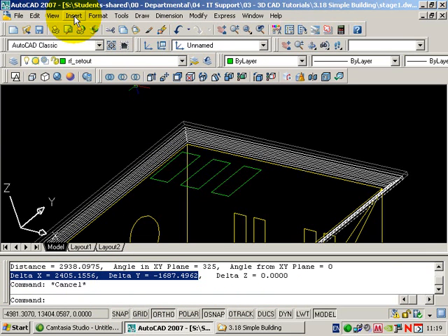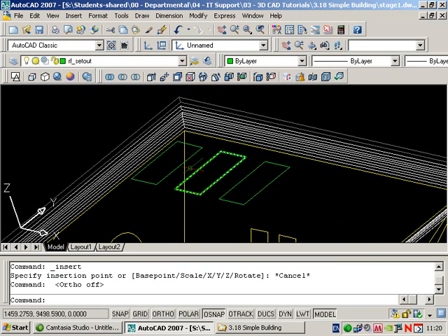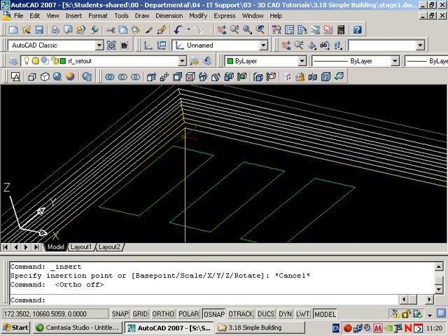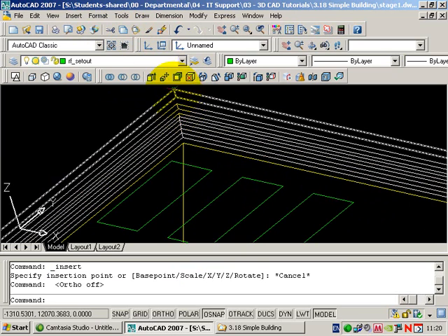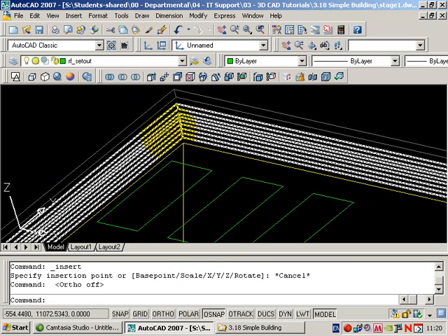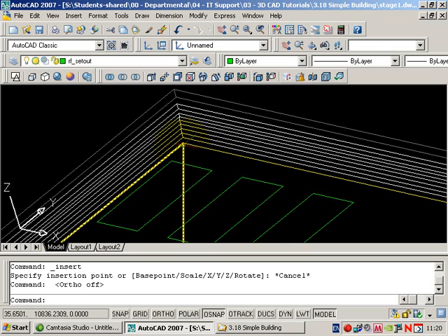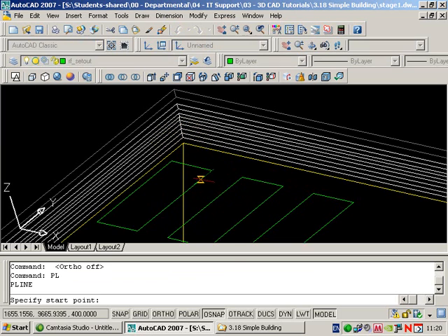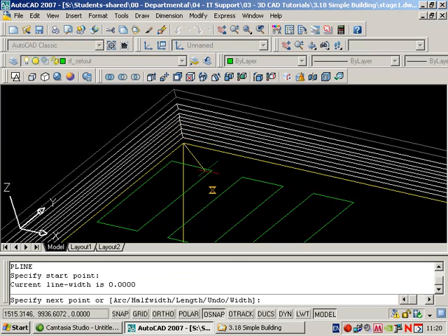So I want to just check my notes, and I realise that I need to extrude these by the depth of the roof before I can bring in the roof light block. But how thick do I need to make that? Now I can use the screen to help me. I'm in the roof plane UCS, so if I drew a polyline from this corner to this corner, it's going to give me the height, the thickness of the roof overall. So PL, return, from corner to corner.